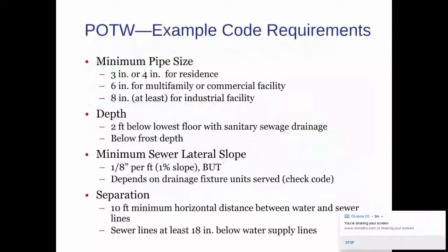And in order to make this all work, as with most things in civil engineering, there's codes because we've found what works and what doesn't work. So if you are looking at a typical sink, like in your kitchen or in your bathroom, you'll notice that the water comes in. It's usually pressurized. It's in smaller pipes, like half-inch diameter pipes. You might have some lines that are up to 3/4 to an inch, if that's the main service into your house. But once it gets to the faucet, it's usually about a half-inch pipe.